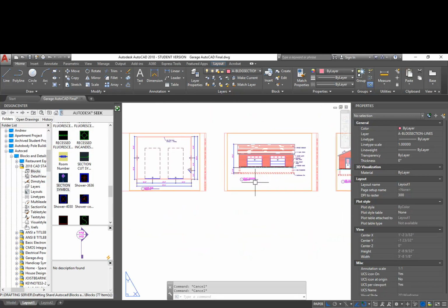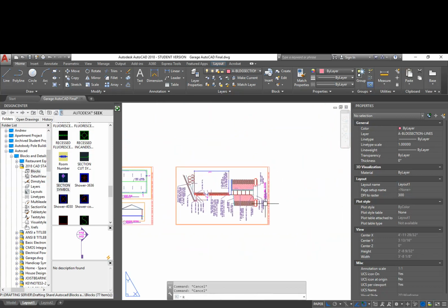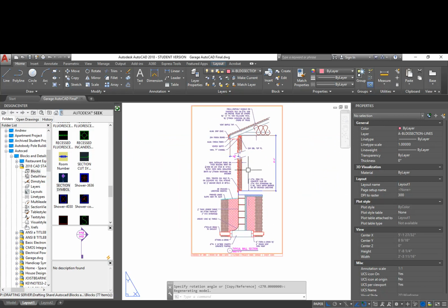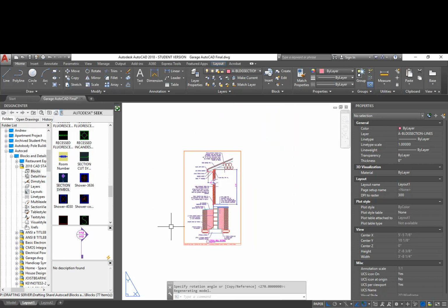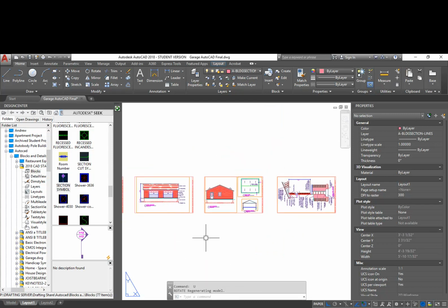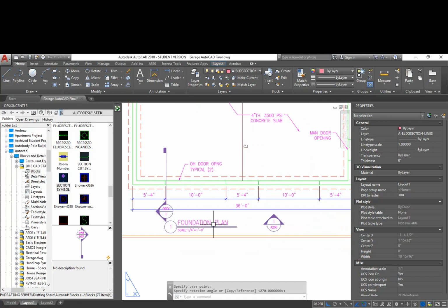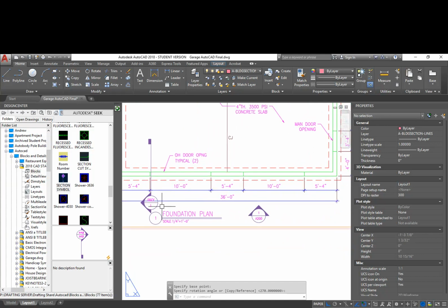So whenever I look at this drawing, and we'll just see if we can rotate this real quickly. If I'm standing here looking at this, the inside of the building is on my right side. So that symbol isn't correct. So what I need to do instead is I need to rotate this whole thing this direction, and I'm just going to move it down here, move again,